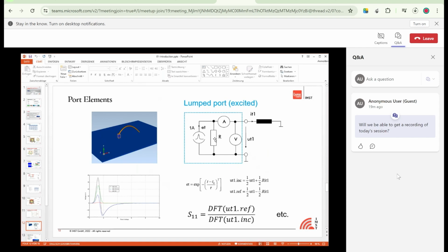Usually we use 50 ohm resistors for ports, and we have a measurement of the current and of the voltage. So these are in principle 4 elements which are inside of a port. Outside of the port, this can be approximated for low frequency with an inductor, and then we have the ground plane here. And this is the equivalent circuit for this structure, but only valid for low frequency.